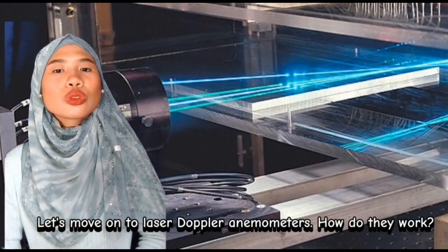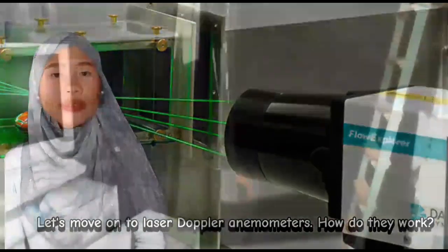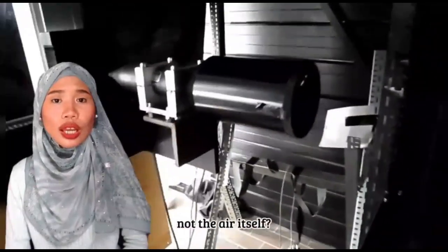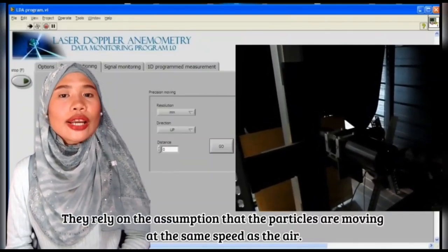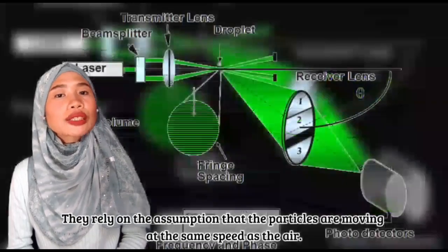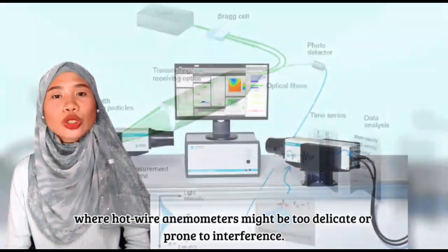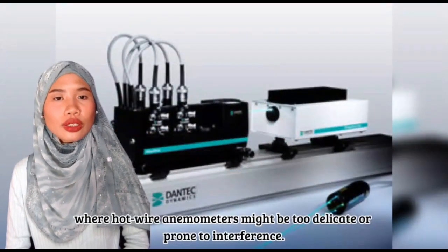Let's move on to the laser Doppler anemometers and how they work. Laser Doppler anemometers measure the speed of particles in the flow and not the air itself. That's right. They rely on the assumption that the particles are moving at the same speed as the air. Laser Doppler anemometers are particularly useful for measuring wind speeds in situations where hot wire anemometers might be too delicate or prone to interference.